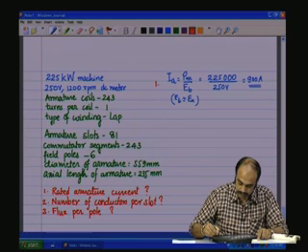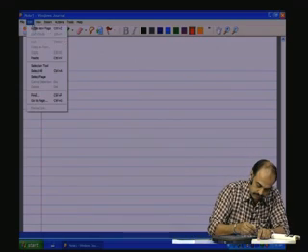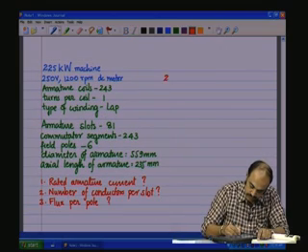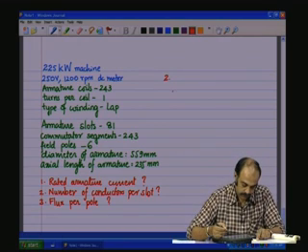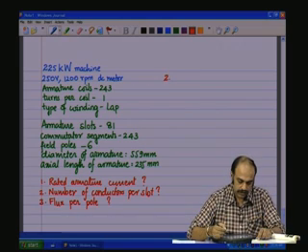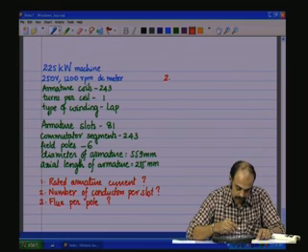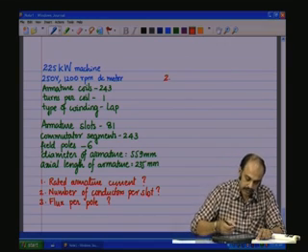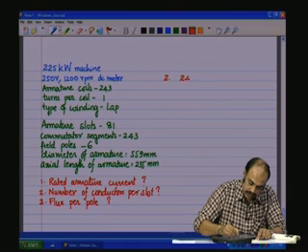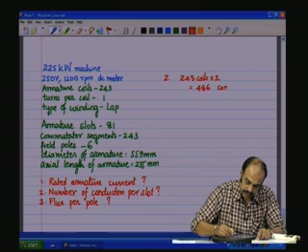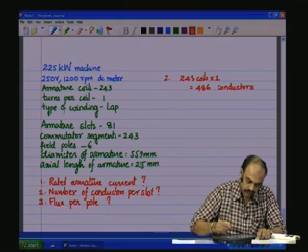Now, let us take the second portion of the problem. So, we have it here so that we can refer back to these values. Now, each coil is made up of 2 conductors, as we saw. Each coil has 2 conductors. So, there are 243 coils, and therefore, 243 into 2 conductors. So, you have 243 coils into 2, which is equal to 486 conductors on the armature.